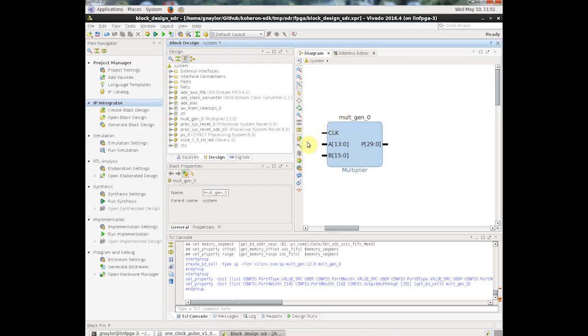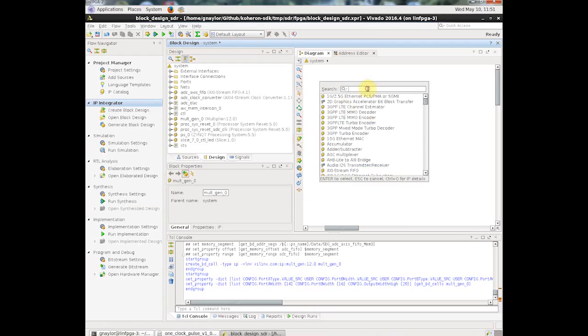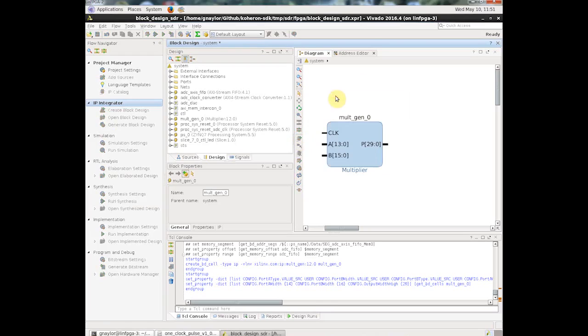So what we'll do is start with a CIC filter to do the first step, a big decimation step, and follow that up with an FIR filter to tidy up the response and get a nice tidy low pass filter down at the sample rate we need without using a huge number of coefficients that we would need if we wanted to do this in a single FIR filter. So let's pull up the CIC filter, CIC compiler. Okay, let's go for that.